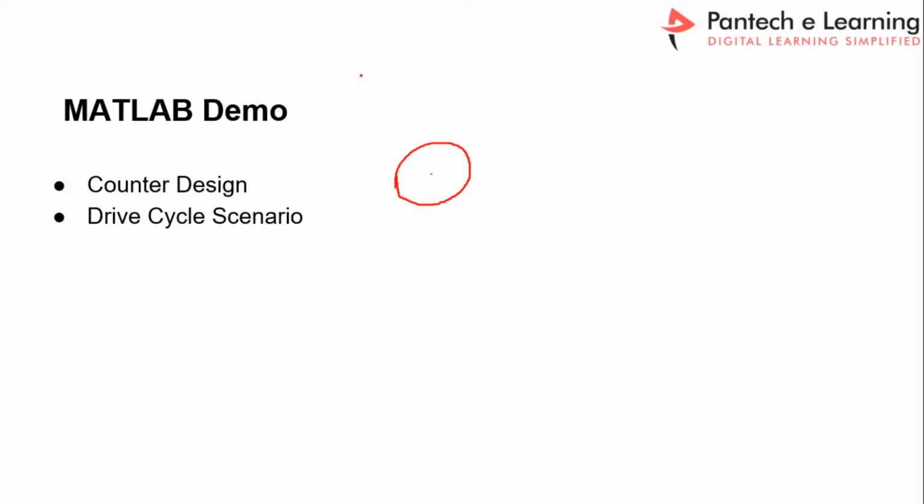That speed sensor may be a magnetic sensor or a pulse or optical sensor. From that sensor we can get square pulses, right? Now by counting the number of pulses, we can identify the RPM.